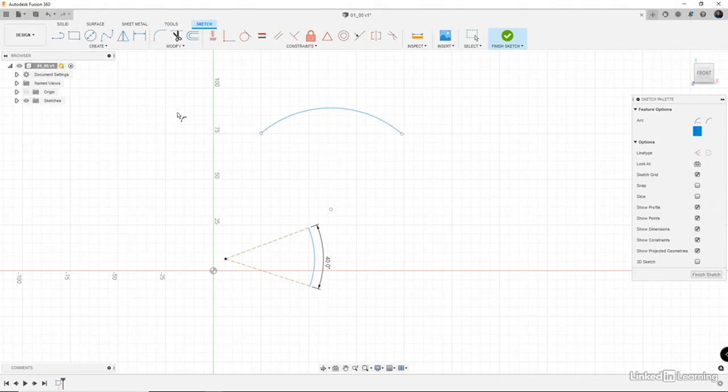And then we also have another tool, which is one that I actually use quite a bit. It's the tangent arc. Now, tangent arc is cool because you can specify the endpoint of any segment, and it will create an arc that is tangent to the end, and you specify the radius. So we could, for instance, do something like this, and then specify another one, and we can have it be that same center line, but alternating radiuses. So you can create some really interesting shapes very quickly using it.